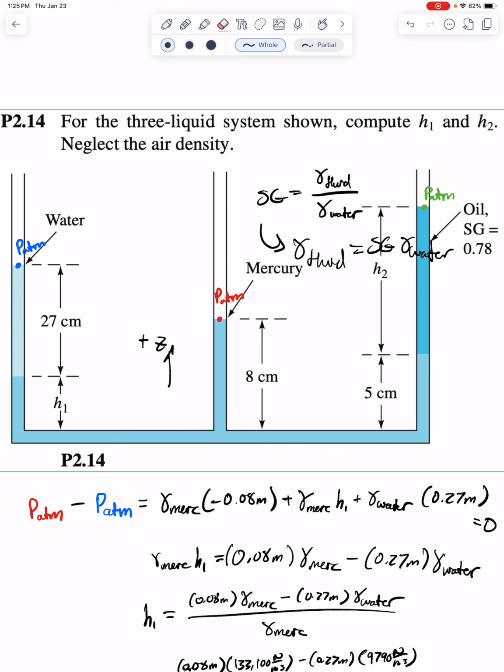But is the bottom the same shade as the mercury? Yes, same shade as mercury. So isn't the bottom the mercury? Yeah, it is. So this whole section, is the lower height always negative because it's pushing the other fluid upwards? Is that the idea? Oh, sorry. So since the mercury meniscus is at a lower level than that of water and oil,